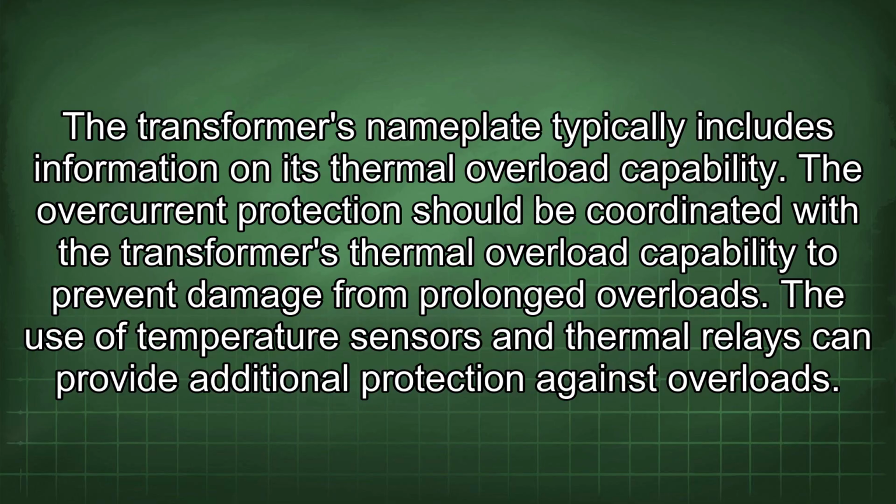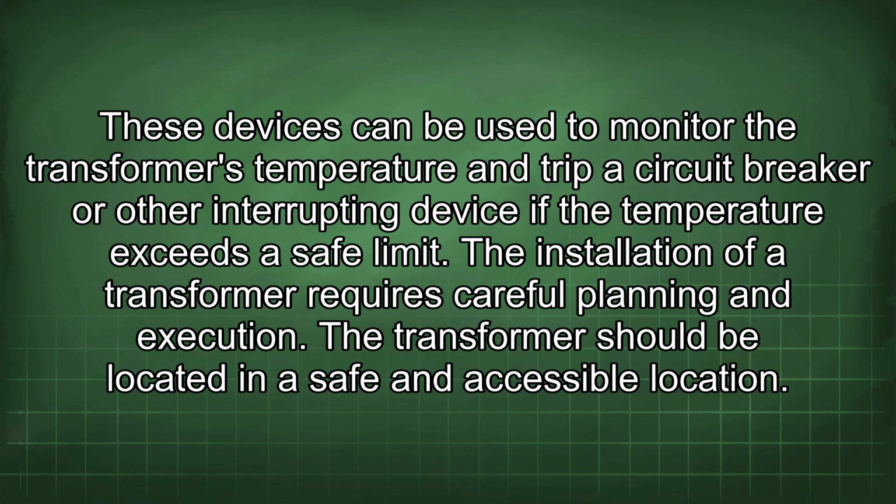The use of temperature sensors and thermal relays can provide additional protection against overloads. These devices can be used to monitor the transformer's temperature and trip a circuit breaker or other interrupting device if the temperature exceeds a safe limit.